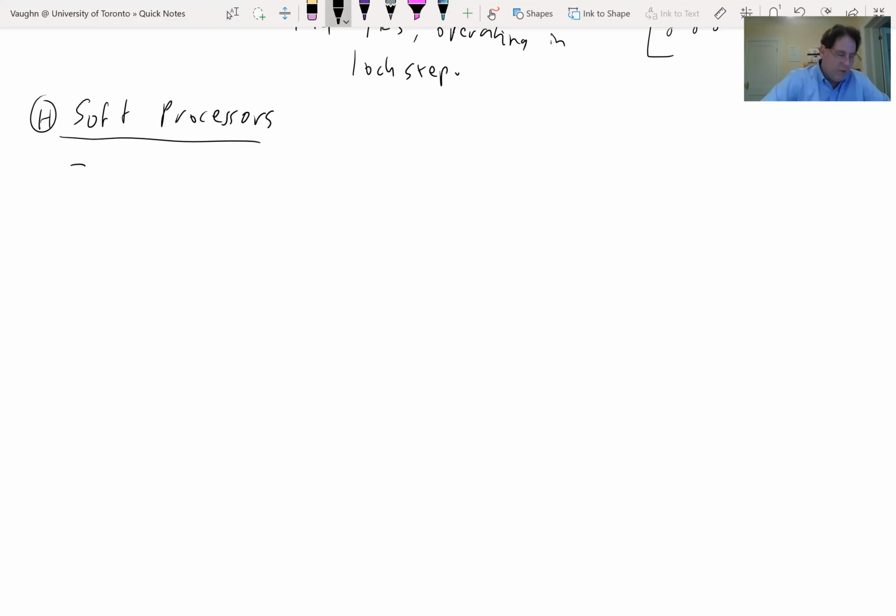So the basic place where this makes sense, in my opinion, and there are other people who have different opinions, is that it's useful for housekeeping. It's basically useful for things where you don't need that much performance. So where would that be? FPGAs enable very large hardware systems nowadays. So there may be some setup, some initialization, and putting that all in a big finite state machine can be a pain. Or there may be some error conditions that are rare, etc. Things where you don't care that much about performance, but the logic's relatively complicated. So you can use a soft processor for those.